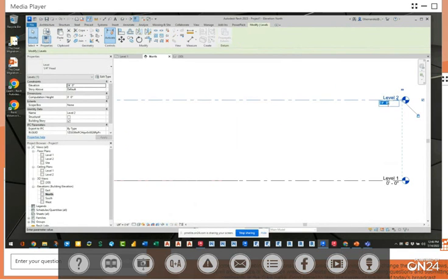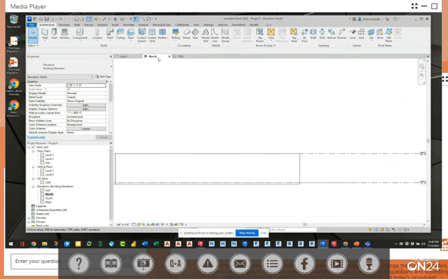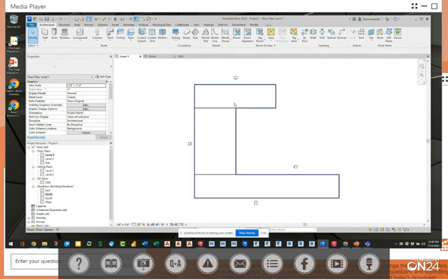And that's again why you start here with these first, and then when you generate the geometry, you can go back. You don't have to be perfect with everything. You can go back, get your design laid out, put in your floors, your walls, doors, and windows, and then you can massage it, or fine-tune it, after the fact.